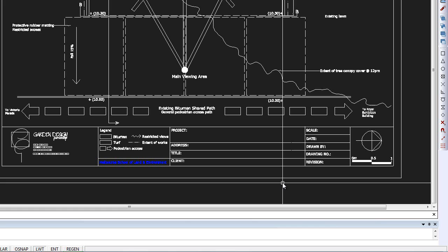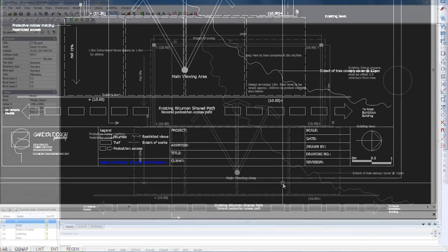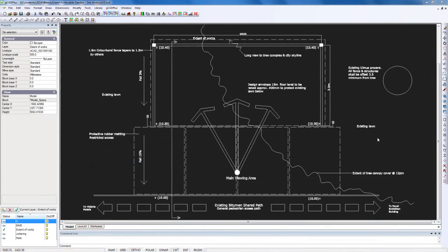And that creates a great deal of difficulty for all sorts of reasons, not just for controlling line weight, but for controlling a view of the model. So let's have a look at how you might repair the situation. Well, what I've done is to remove all the entities that have been placed in the model space that have nothing to do with the physical design itself, and I've put those into a layout space.